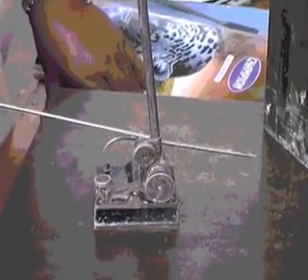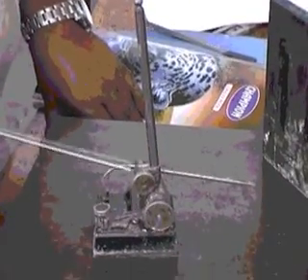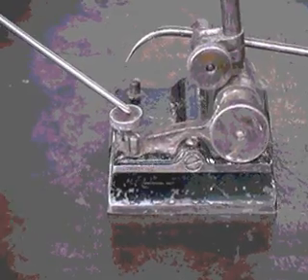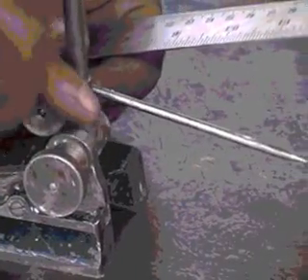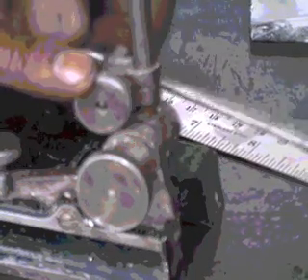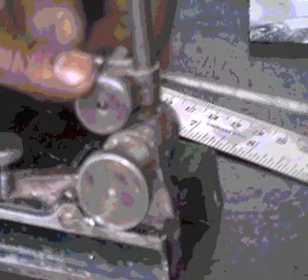This is a scale. This is a universal marking gauge, or universal scribing gauge. This is the fine adjustment screw. We loosen the scriber from this screw. The scriber is now free. Our aim is to mark a given position using this scriber, using this universal marking gauge.